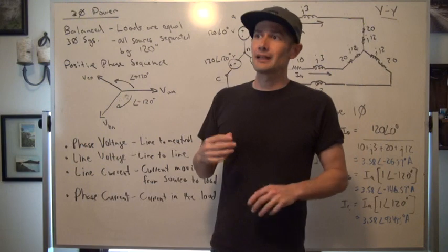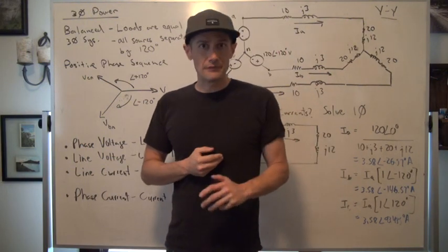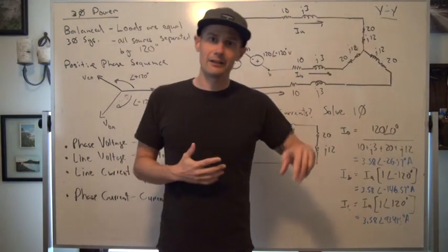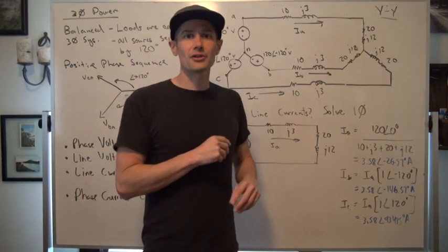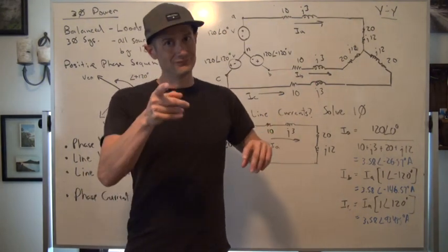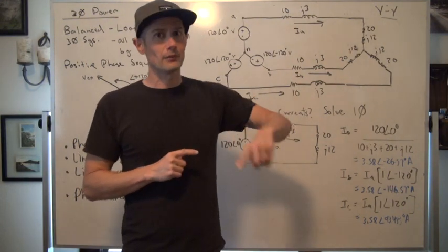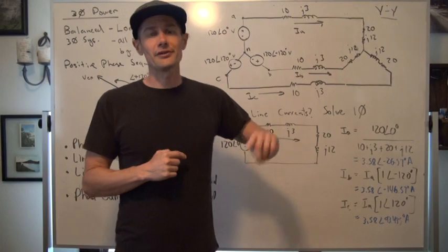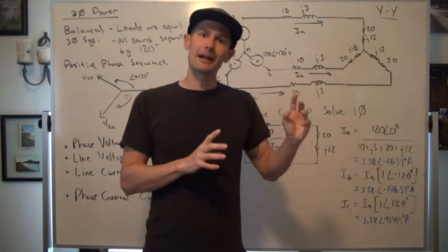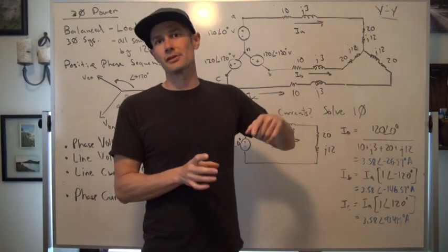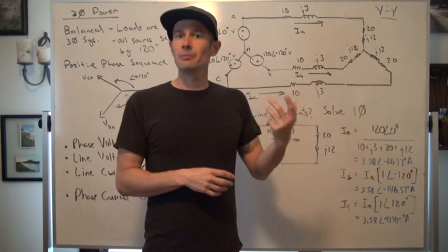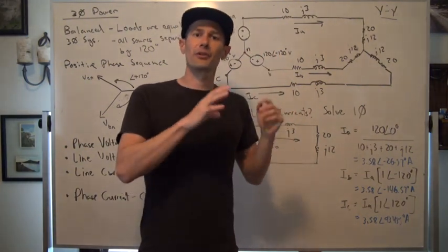Well, when we look at the generator, which is what we've talked about a couple of times in class, and how AC is generated, we have a rotor that has a permanent magnet and it spins 360 degrees. Instead of just allowing that permanent magnet to spin amongst one coil, we allow it to spin amongst three coils.